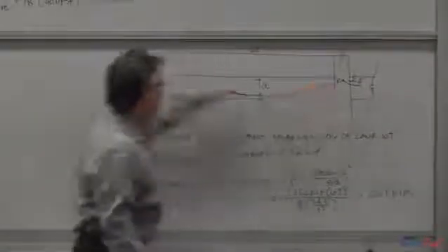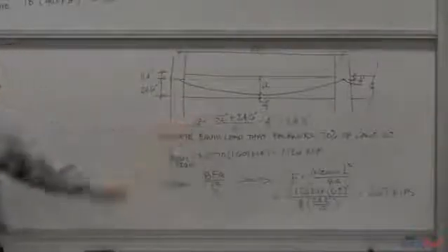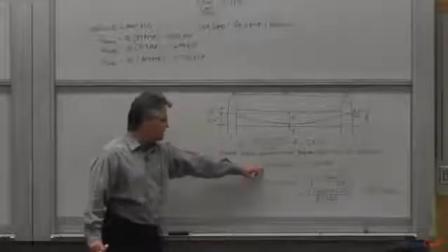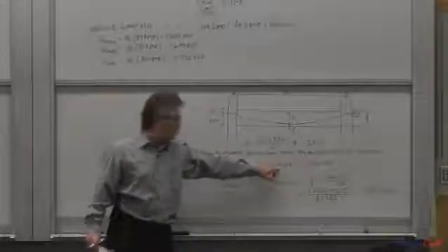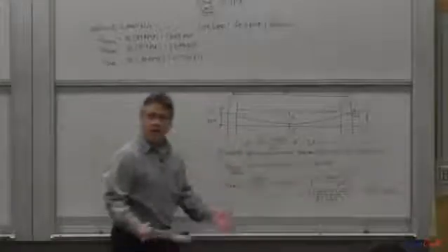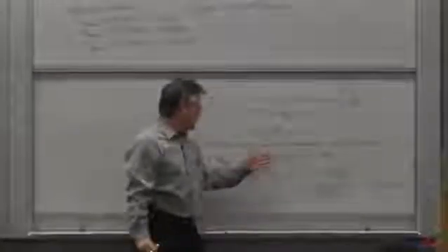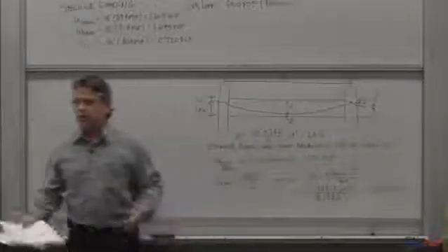Okay, I already know what a full drape looks like. I don't need to know what the force is to know that the most A I can get is 24.3 inches in this span. I've asked you, or I've asked me, to balance about 70% of that concrete weight. That concrete weight was 1.609 kips per foot. Just the weight of this beam and that 5-inch slab is 1.609 kips per foot. So I'm going to try to offset that by 70%. So 0.7 times that is 1.126 kips per foot. That's what I want to shoot for as a balanced load.